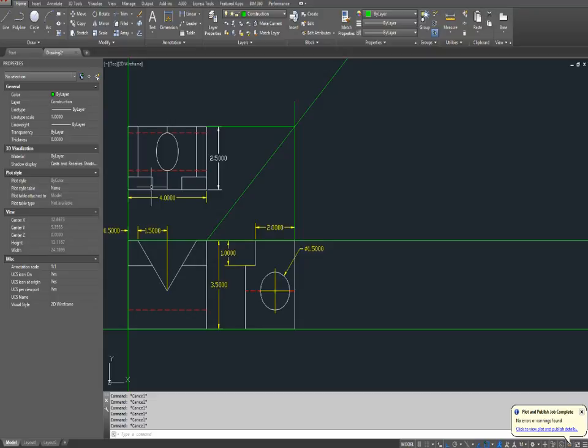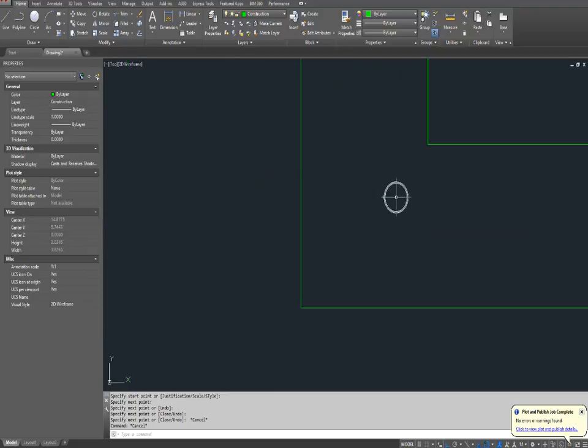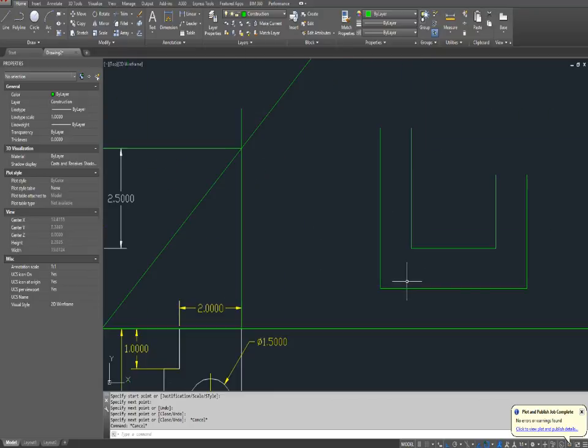So then if you want to make multiple lines, mline, I can use the mline command, and you can see it's creating multiple lines. And the big advantage here, like if you're working on something like a floor plan, is that you're saving a little bit of time because it's trimming out the corners for you.